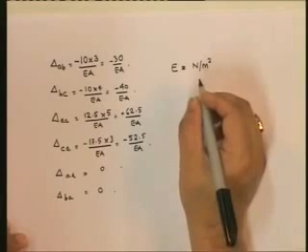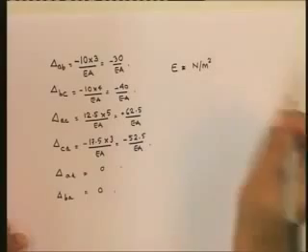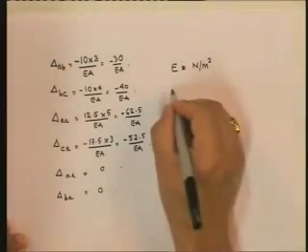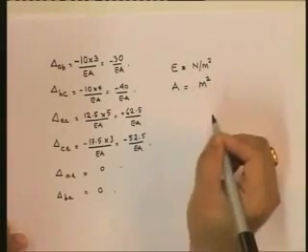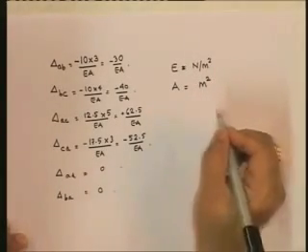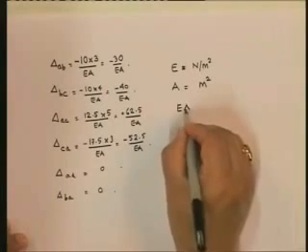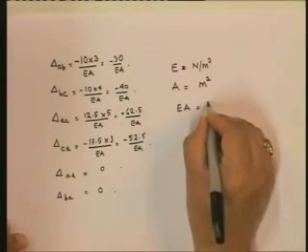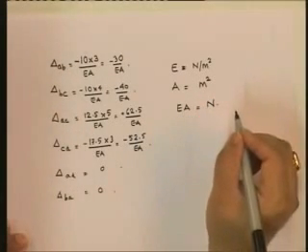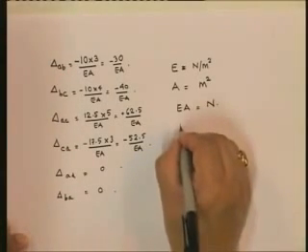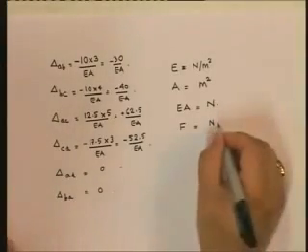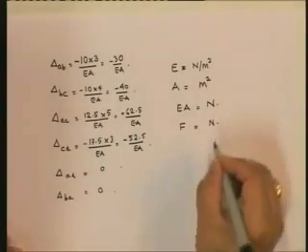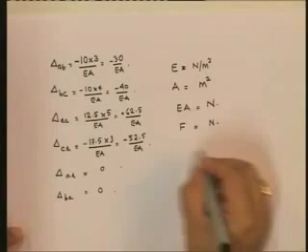Stress is Newton per meter squared. Strain is meter per meter, so strain does not have any units. Then what about the units of area? Area is in units of meter squared. So what is EA in terms of? It's in terms of Newton. What is force in terms of? Well, I've given kilonewtons here, but a kilonewton is nothing but 10 to the power of 3 newtons. So the basic unit is Newton.